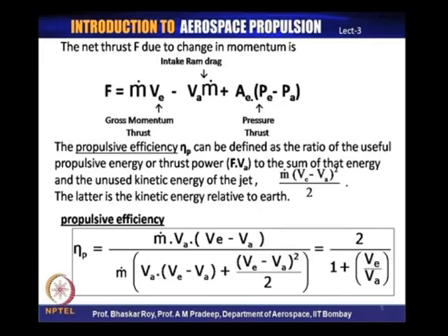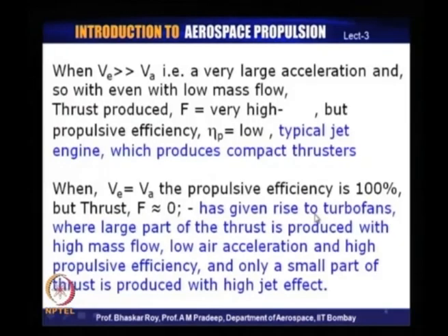As you can see here, the propulsive efficiency is thus dependent solely on the ratio between the exit velocity and the entry velocity of the working medium, that is air, and that clearly gives us a quick and handy idea what is the efficiency with which this propulsive device is most likely to work. Now, the fallout of this very simple propulsive efficiency definition actually tells us a few stories. Let us see what actually can be extracted from this very simple definition of propulsive efficiency.